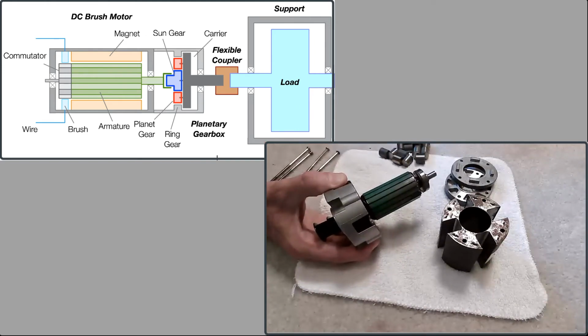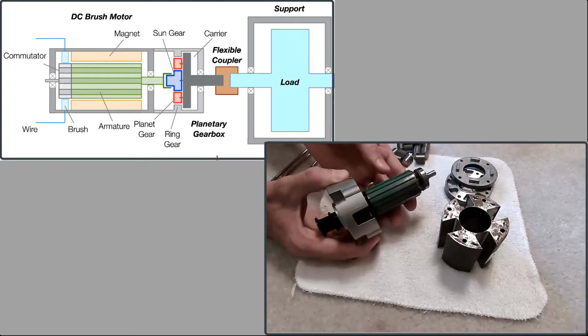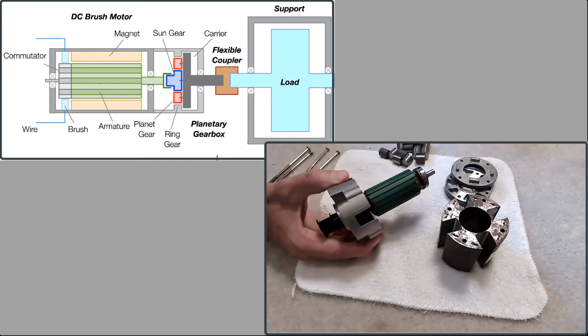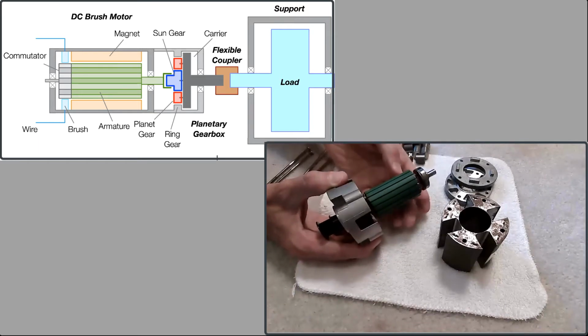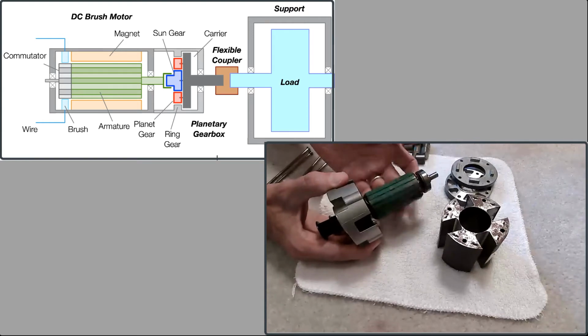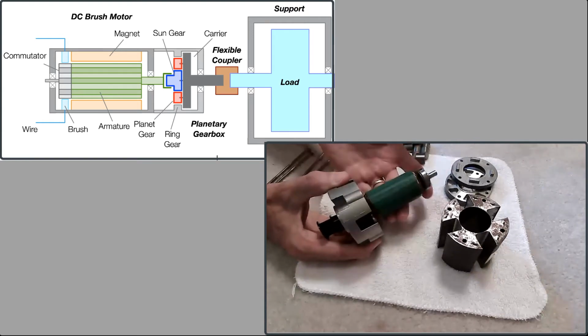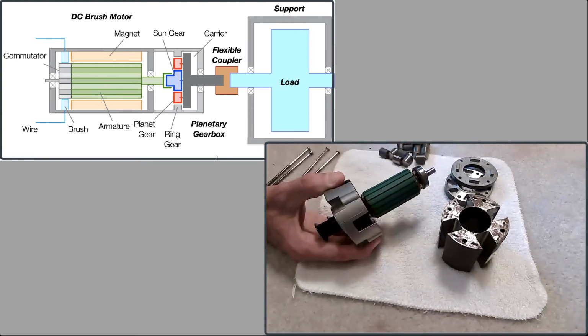So if you were to calculate the mass moment of inertia of the armature, you would take a half times its mass, which is another half a kilogram, times r squared, 0.015 meters squared. So you get about 50 times 10 to the negative 6 kilogram meter squared. Sounds like a small number, but that's actually fairly significant.